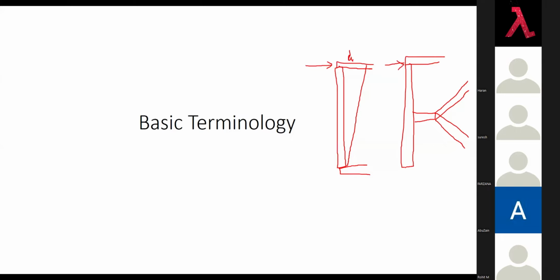In this case, when we apply this load, it is not free to move from here. It will deflect from here because this slab is holding it. This slab's horizontal rigidity is high, my horizontal stiffness is high, so it will stop here. My beam will deflect on this side. We have this drift. Now you can ask, what is the problem?